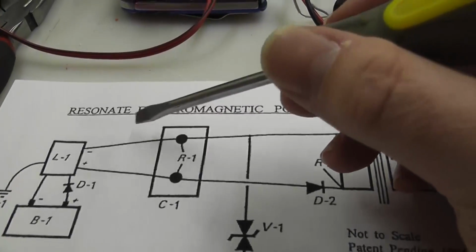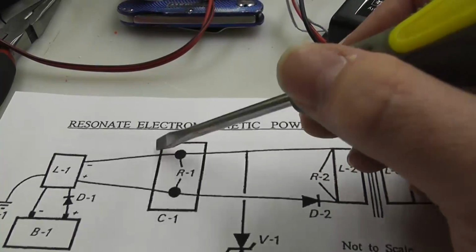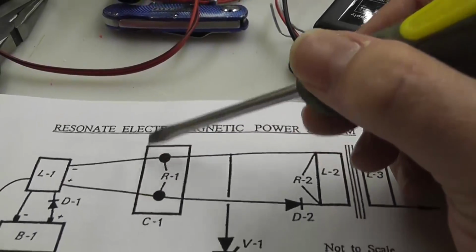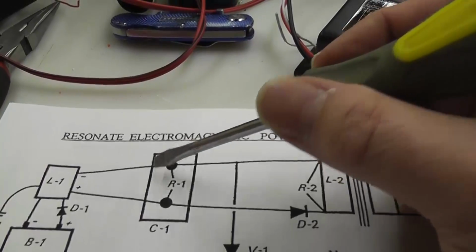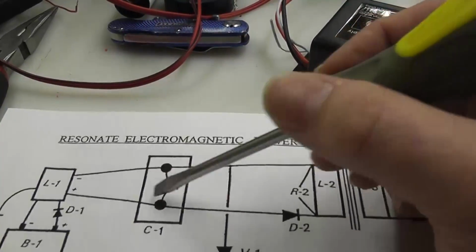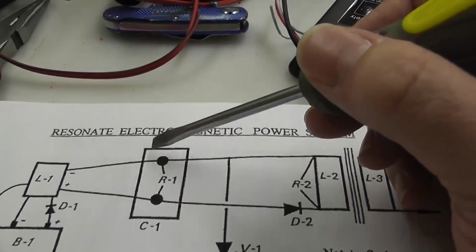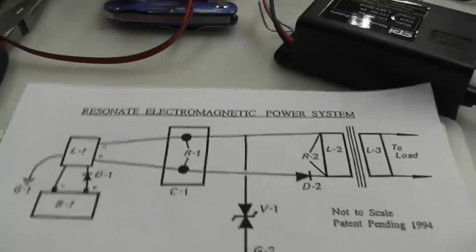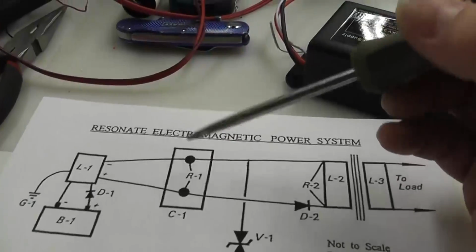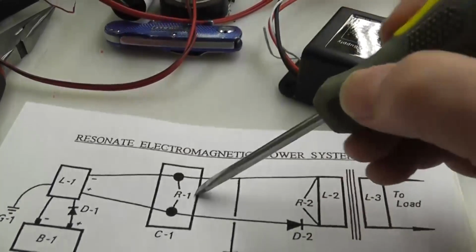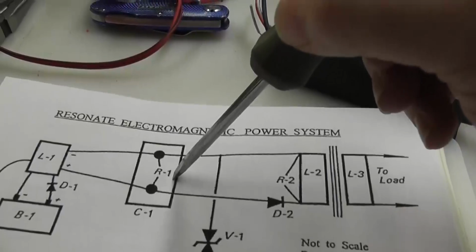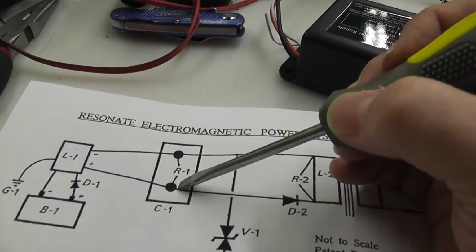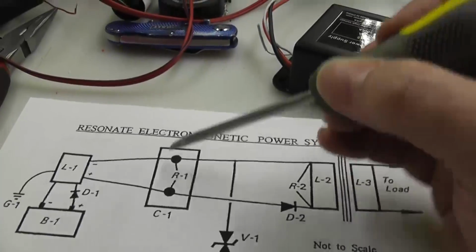You'll see that normally with this open, measuring with just a voltmeter, you get around 150, 200 volts. But once you put a capacitor in there, it runs through it just fine, depending on the frequency you've got. You have to tune in the resonant frequency, which is the nice thing about a frequency generator. You can change it to whatever you want. And once you get the resonant frequency with whatever capacitor you're using, you get the max voltage. Now you drop a resistor across there, and depending on the size of that resistor, if it's small, your voltage goes down.